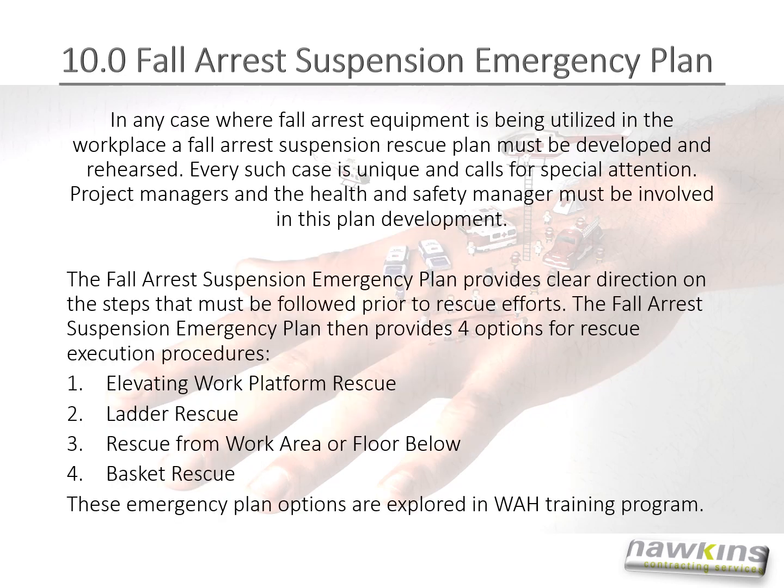In any case where fall arrest equipment is being utilized in the workplace, a fall arrest suspension rescue plan must be developed and rehearsed. Every such case is unique and calls for special attention. Project managers and the health and safety manager must be involved in this plan development. The fall arrest suspension emergency plan provides clear direction on the steps that must be followed prior to rescue efforts. It then provides 4 options for rescue execution procedures.